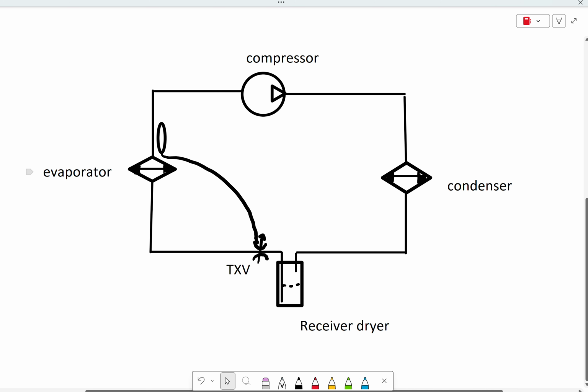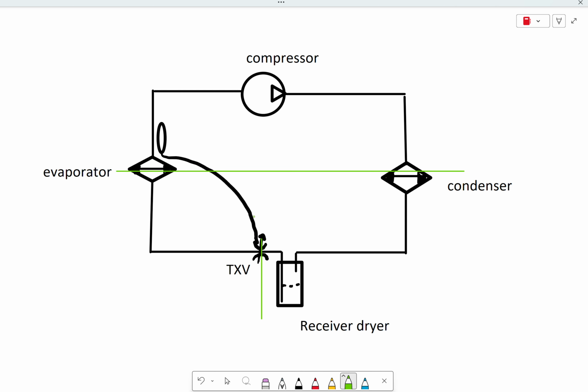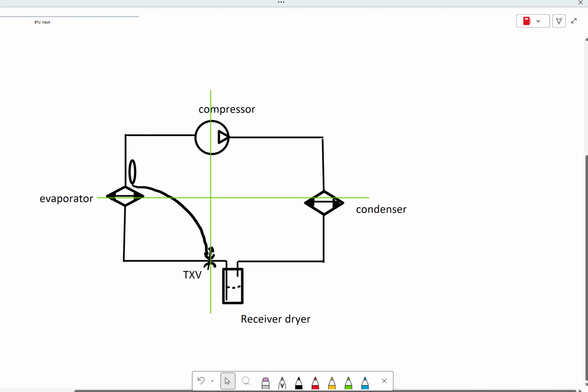Now, when you guys did your AC training in previous levels, you probably discussed that this system kind of has 4 different quadrants to it, right? And those quadrants have different things happening in them. So, for instance, over here, we might have the compressor. If we think about what the state of the refrigerant is, what is it? It's a gas, okay? If I was to use a thermometer and measure the temperature coming out, would it be really hot or really cold? This would be hot.